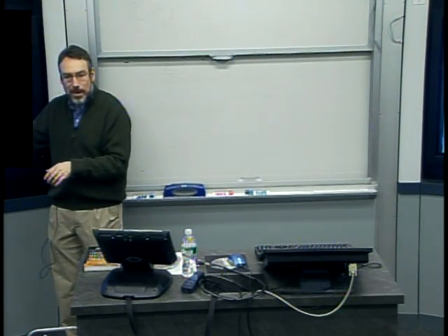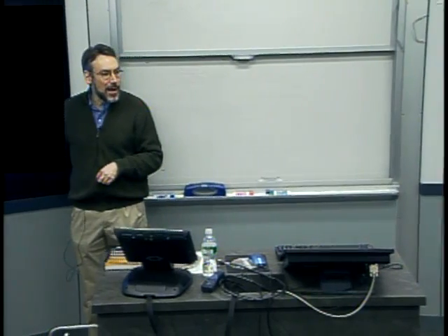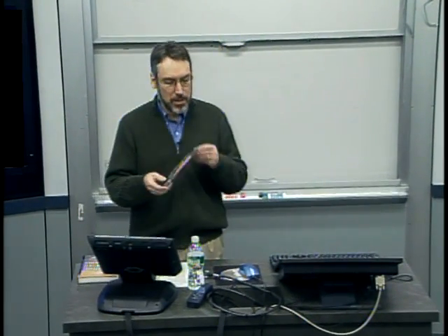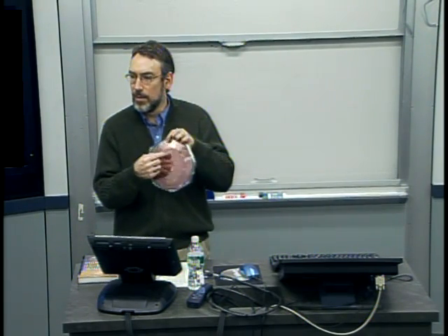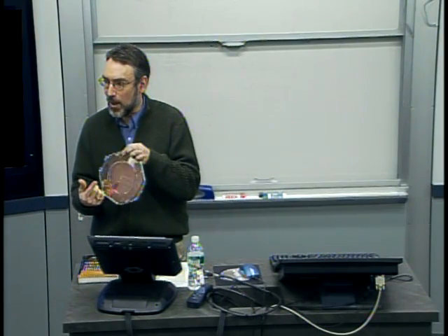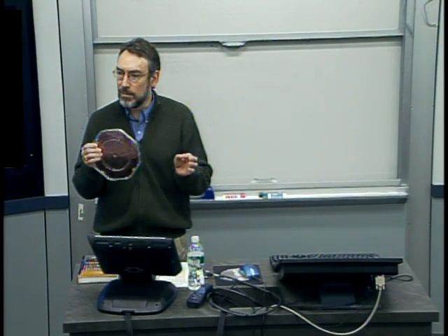Imagine that I don't need to line up just for one transistor. I've got to make sure across maybe a 1 centimeter squared or 2 centimeter squared chip that all of my transistors are lining up. And in fact, in older technologies, I had to make sure the whole wafer was lined up because I had a big glass plate that I was using in almost a 1-for-1 transformation. So everything across the whole wafer had to be lined up. And if the temperature of the glass plate and that of the wafer were off by a degree, the thermal expansion would upset the alignment, for example.